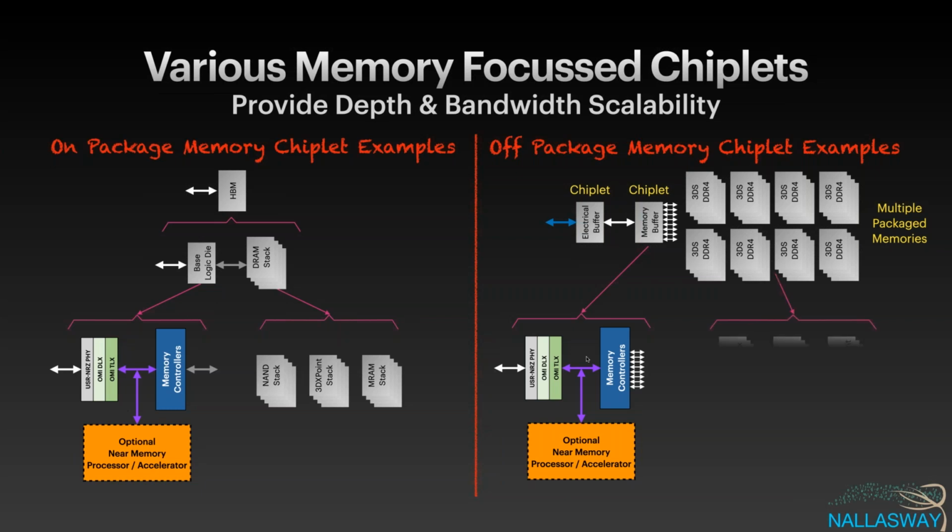And again, we can change those memories from DDR4 to LPDDR4. It's got some very nice characteristics in terms of speed and low power. We could put 3DS NAND, 3DS X-Point, or interestingly, we could even put HBM. Imagine putting 8 HBMs to a tiny memory buffer die, and then you would have some local processing, but you would be able to shrink down to maybe a smaller interface and have many of those HBMs.